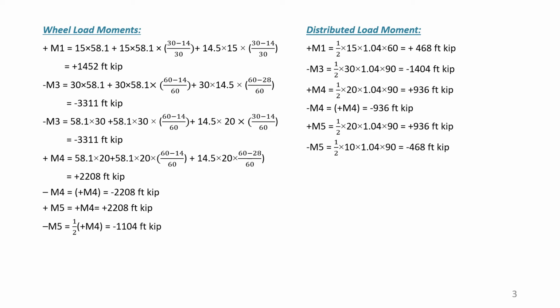This is 20 kip feet per kip of load. Next we will go to 0.5. If we put a load of 1 kip at 0.5, there will be a reaction of 1/3 on the left hand side and a reaction of 2/3 at 0.6, and if we multiply this 2/3 by 30, the maximum ordinate is again 20.